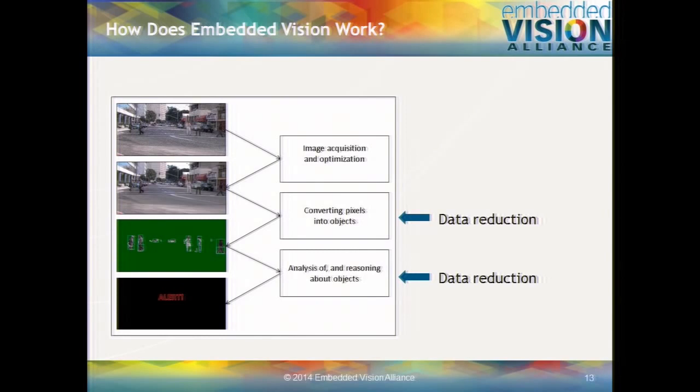There are applications like factory automation where imaging conditions can be very tightly controlled. For example, imagine a bottling plant where beer bottles are coming down a conveyor belt, and the job of the vision system is to make sure that each beer bottle is filled to the appropriate level, has a cap affixed, and has the label affixed. Well, what we can do in a case like that is make sure there's nothing in the background that's going to make the problem harder. We can make a really simple, plain background. We can have optimal lighting from the same vantage point as the camera. We can locate the camera in exactly the optimal position to get the best quality image. And that's what they do in factories, and it works great.